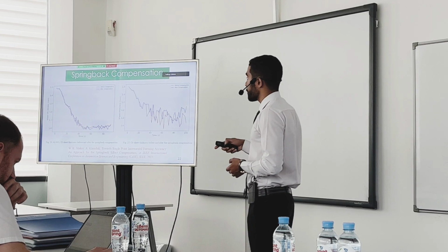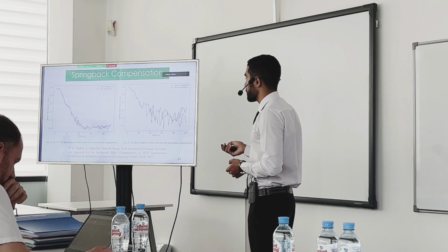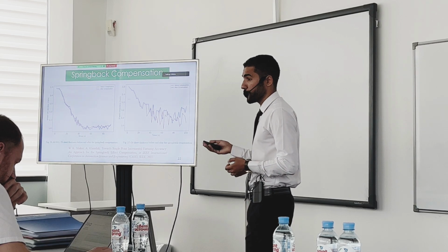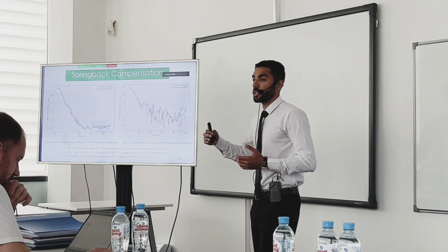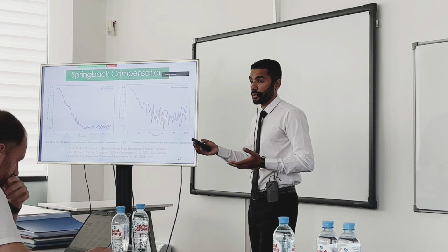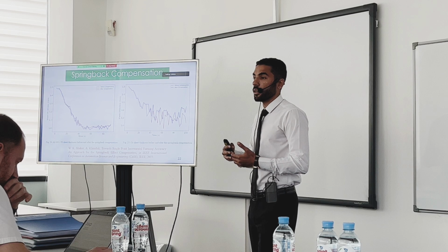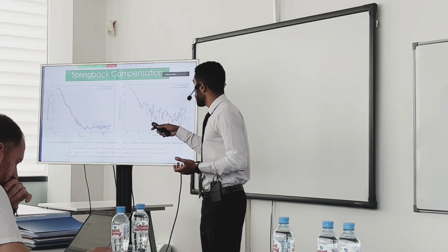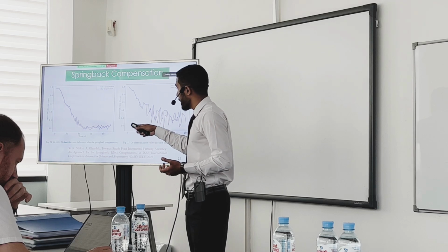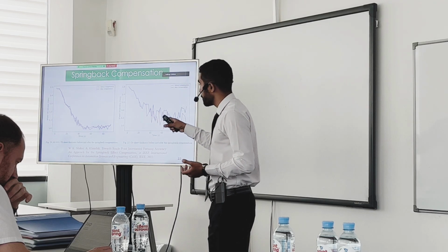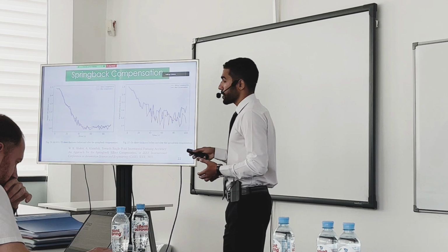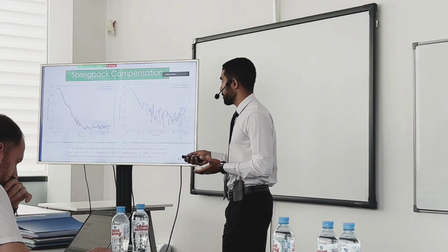Another key advantage of this proposed model is that it doesn't affect the sheet thickness much. It will not impact the thickness of the material in a negative way, I would say. For example, in the aluminum, there was a reduction of sheet thickness by almost 30%, which is normal behavior in incremental sheet forming.